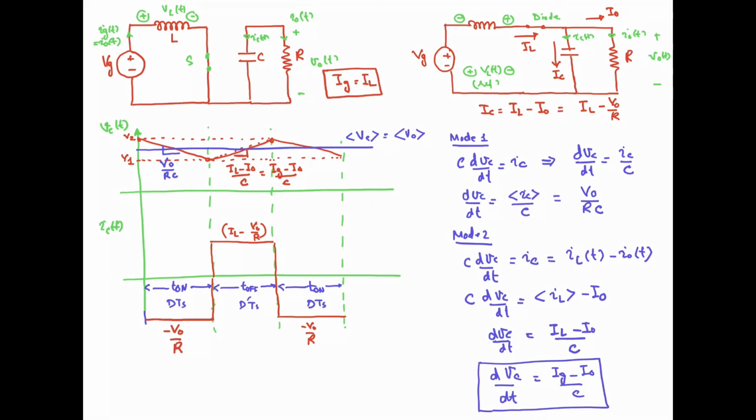So we have defined the slopes for the capacitor voltage waveform. Now the average current through the capacitor should be equal to 0, that you know from the basic operation of the capacitor. So the area under this waveform should be equal to 0, right, considering one cycle. So in the converter, this average area should be equal to 0. So now we are basically applying the ampere second balance. Ampere second balance for the capacitor should be equal to 0. That means the area under the current waveform should be equal to 0.